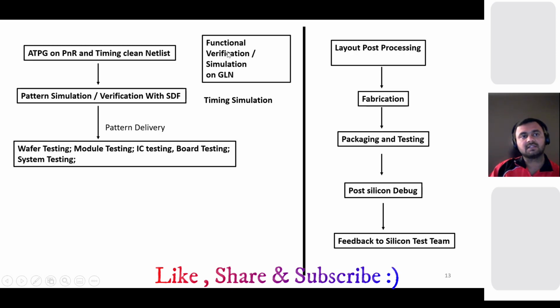And in parallel to that, on the same PNR netlist, the functional team also verifies the functionality, because ultimately that is the netlist which will be taken further for the fabrication of the chip. So on that netlist, everything should be clean with respect to timing. So the test team performs the ATPG, and then the functional team performs their functionality checks. And then in the PD team, they will do the layout post-processing and fabrication, and then there will be a packaging team which will package it and test it. And if that fails, it goes to post-silicon debug and then feedback to the silicon team.